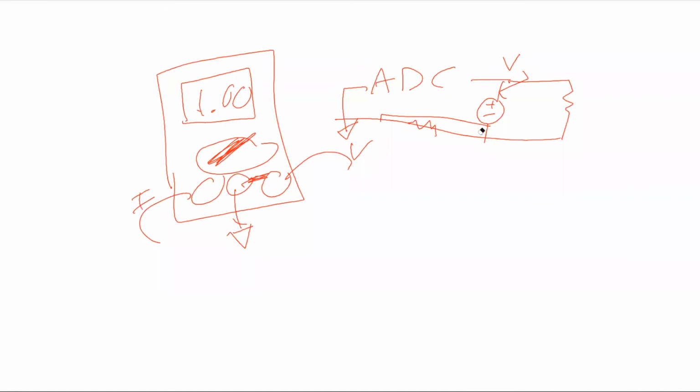And then the ADC is able to measure the drop across this. So there's some voltage drop here. The drop from the I, and it will measure that drop versus this resistor. And it will calculate our R based off of a voltage divider.